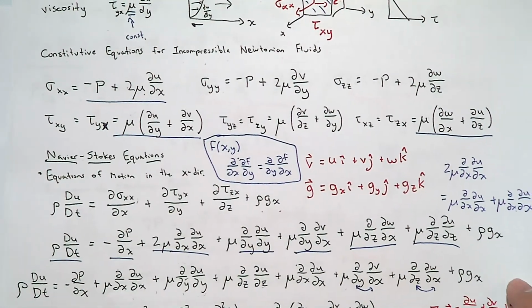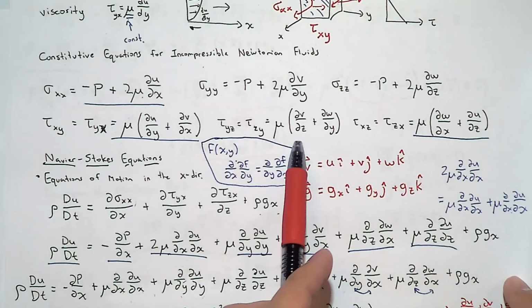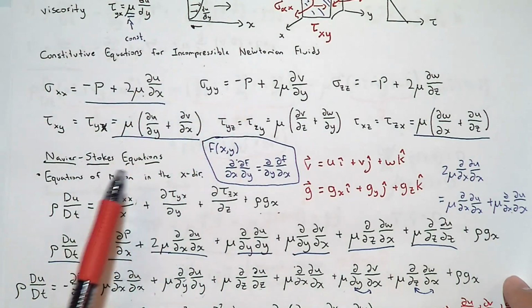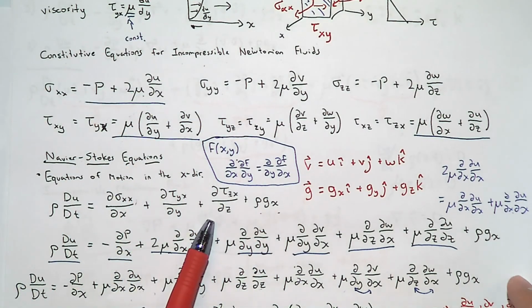If you're looking for non-Newtonian or compressible fluids, you would start with different constitutive equations, then plug them into the Cauchy equations of motion, and then you will land at slightly different equations. They're actually not that different. They look like that, but longer. A little bit longer. You can't just use the formula that we have for non-Newtonian, right? It's just for Newtonian and incompressible.